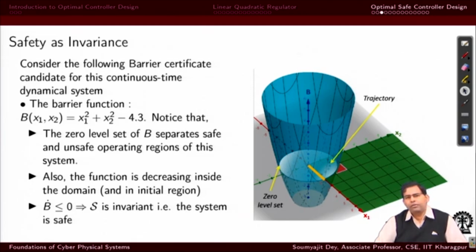If you remember, we need to create a barrier function and prove that this is indeed a barrier function for this system. Or we have to show that if there is a formulation for defining my control law, then the control law always satisfies this barrier function, right. The difference between our earlier method and right now is that earlier, suppose you are given a system and asked to prove that the system is safe or unsafe, we said the system is safe if a barrier function exists for the system.